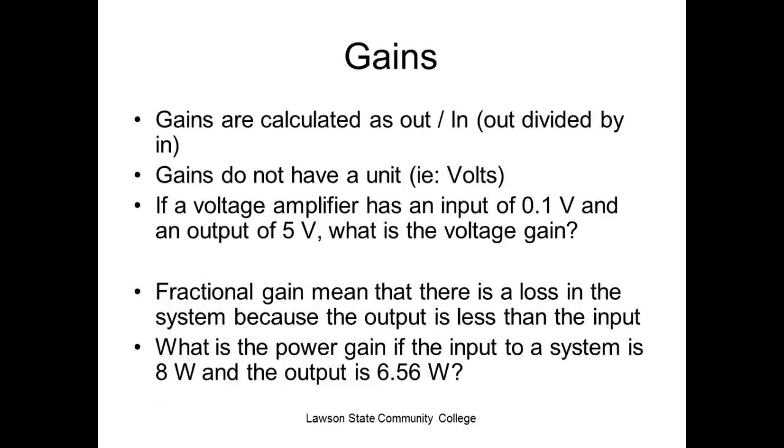Gains do not have units. So if I get a 2.5% pay raise, is that $2.5? Is that 2.5 cents? So gains are just multipliers or dividers. So I could take my output and divide it by my gain, and that would tell me what I started with, right? Or I could take my input and multiply it by my gain, and that would tell me my output. If an amplifier has an input of 0.1 volts and an output of 5, what is the voltage gain?